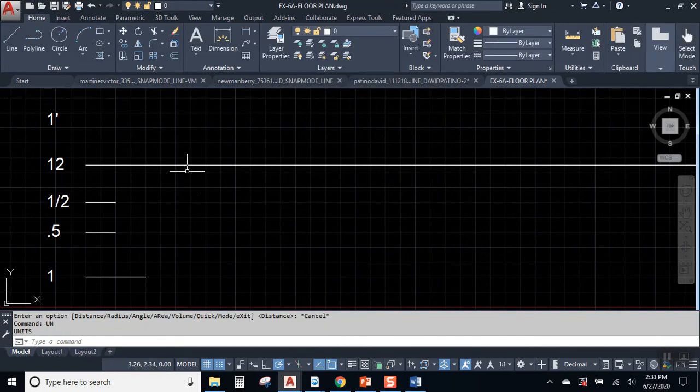All right, so no visible change on the screen really, but look down on the status bar. Do you see how the coordinates are much smaller now? Because now we're only rounding to the nearest 100th of an inch, or the nearest 100th of a unit, I should say. And if I type in F for fillet, I see now the radius, it's saying it's at 0.50. It didn't add the extra zeros because the units are only set to go to the nearest hundredth.